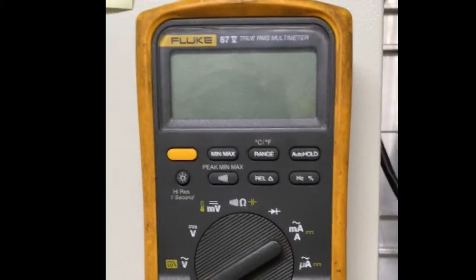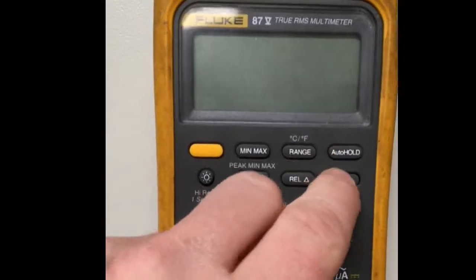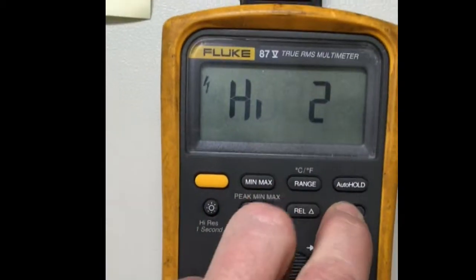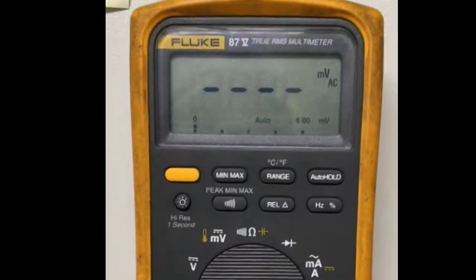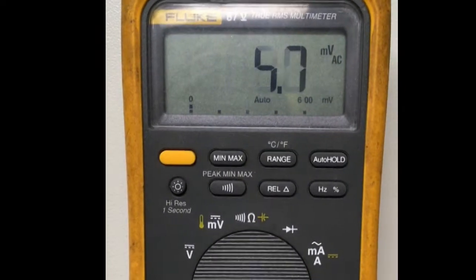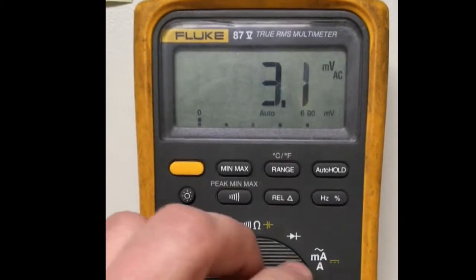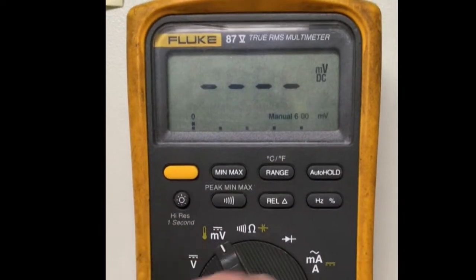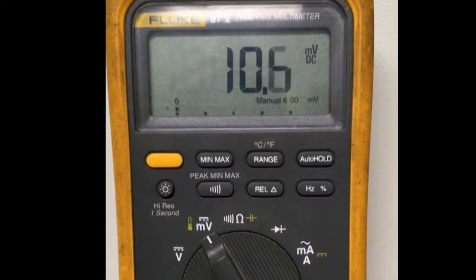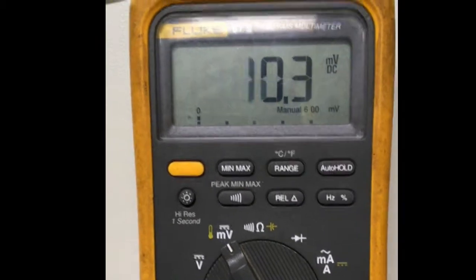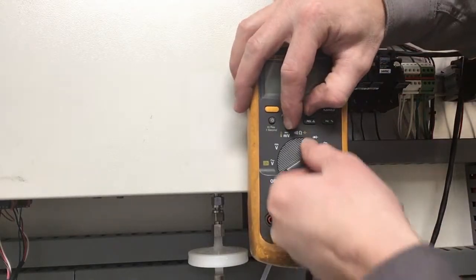For high impedance circuits, a simple voltage measurement in parallel can create a disruption to the circuit. Holding down the Hertz button during power-up places the meter in a higher impedance mode during DC millivolt measurements only. It is possible to activate more than one power-up mode by holding down numerous buttons during startup.